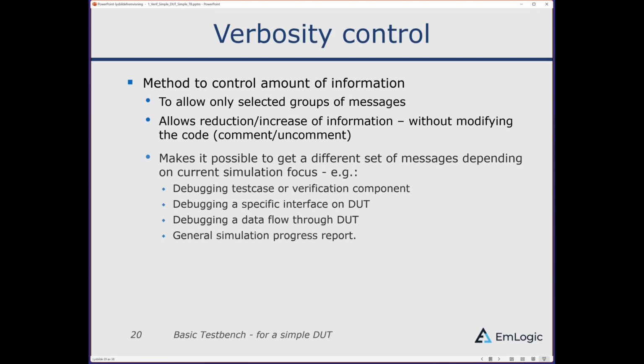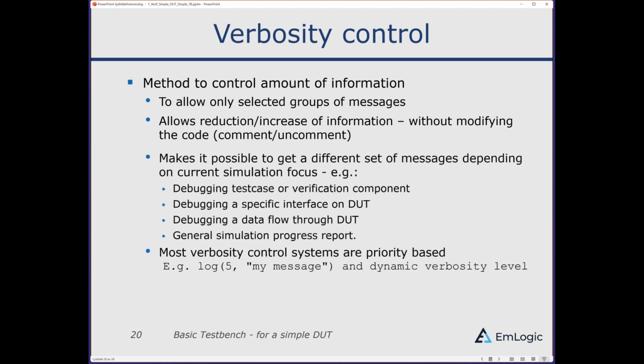I mentioned verbosity control. And what is this? Well, it's a method to control the amount of information coming out of a tool. So in this case, to allow only selected groups of messages. It allows you to reduce or increase the amount of information coming out of your simulation without modifying the code itself, i.e. without going in there and commenting and uncommenting write line statements in your code, for instance.